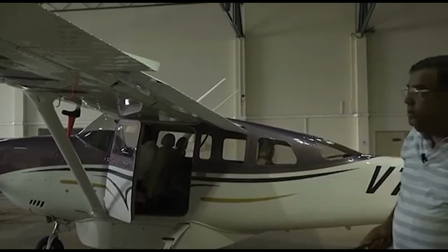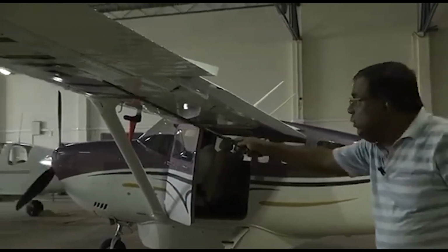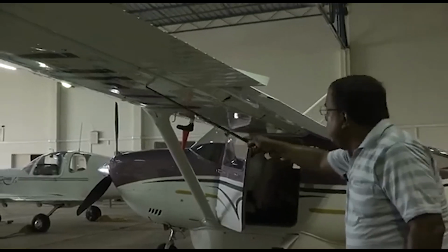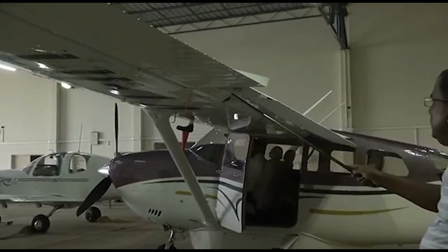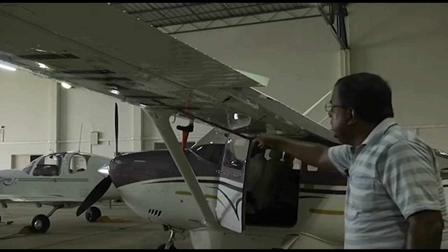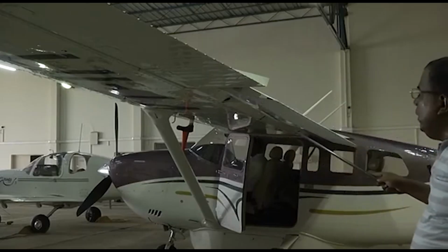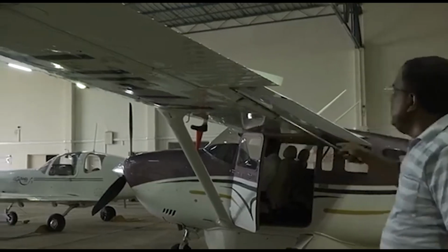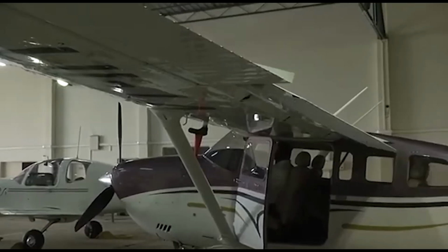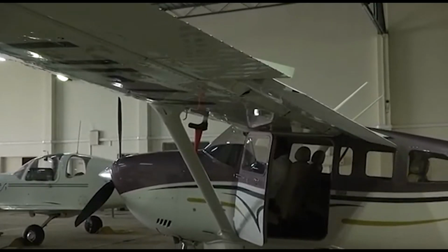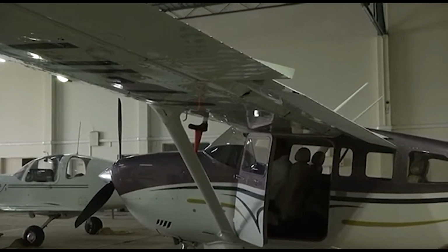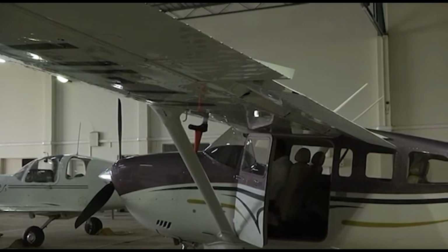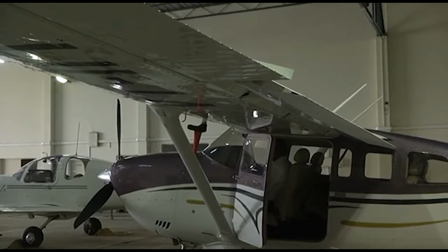What is happening? Please look here. This aerofoil now locally has a camber. Okay? Could you see this? By putting the flap down, it is adding camber to this section. And we know a cambered aerofoil will produce more lift. So that is how the CL max is increased, the lifting characteristic increased, so that you can reduce the takeoff